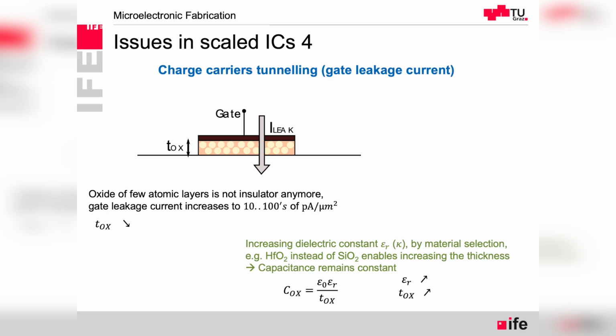However, at some point, when we have started at over 20 nanometer gate oxide, silicon dioxide, then going through 15, 12, 10, 7, 5, and at 3 nanometers, we already can count individual atomic layers of the silicon dioxide there. It's not anymore a good insulator.